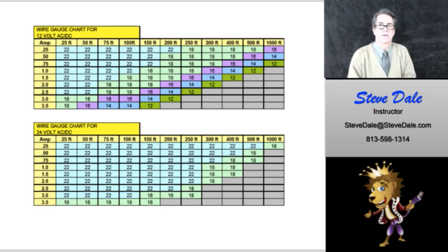Obviously the bell runs off a certain voltage, so you're going to have the voltage constant. So the resistance is going to be constant because you're running the footage out to that point, so you can calculate your current load. Now you have to look at the conductor size to see how much current a conductor can handle based on its AWG number. And that's all in the NEC. So that's all part of calculating loads and everything like that.